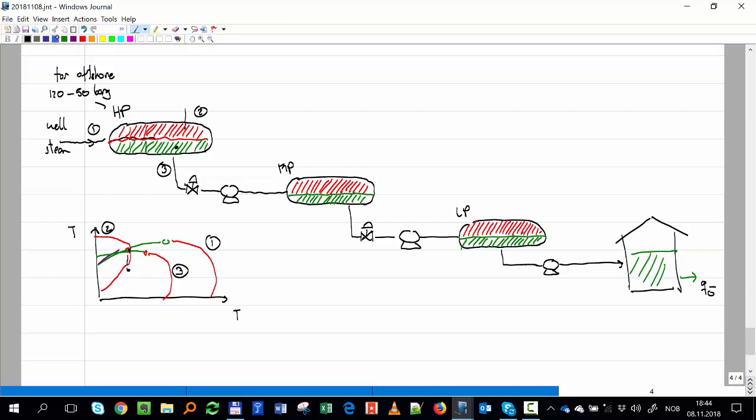If you plot the pressure in the pump, here you have a pipe with the distance, and here you have the impeller. The pressure here is declining, declining, declining, and when you enter, you have a sharp drop, and then you have a jump, and then you have the discharge pressure. This local pressure reduction is inside the pump on the way to reach the rotor. The rotor is where it gets energy, but it has to get there. So it has this local reduction in pressure.